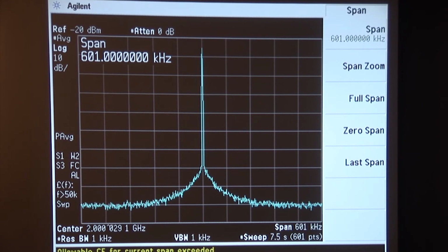That's because when we ended up measuring in a span that exceeds the number of convolution points that we can take with a filter across here, we can actually miss chunks of the spectrum. We do miss chunks of the spectrum, and we can actually fail to get the total correct power.